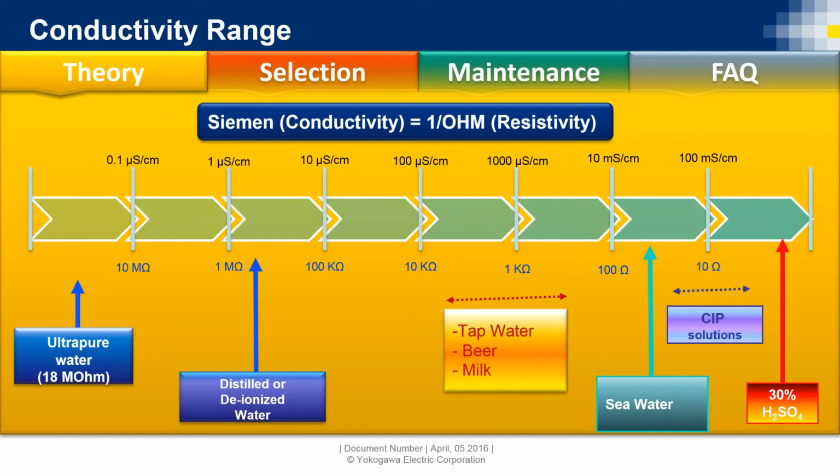When we look at a solution, we see how conductive it is. Again, we have to look at what ions are present in there. Is there calcium? Is there sodium? Are there chlorides? Are there hydrogen ions? Are there hydroxyl ions? Because that's what's responsible for carrying an electric current. Conductivity is simply a quantitative measurement for every ion that's present in there.